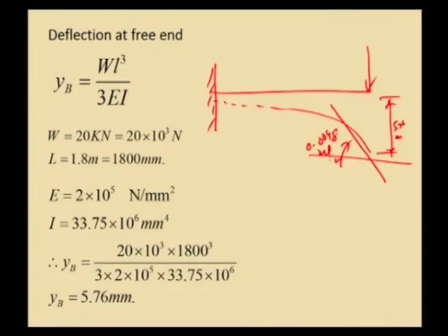So, to summarize, we have started with what is deflection, how do we calculate deflection and what are the equations involved. We have E I d squared y by dx squared equal to minus Mxx. Mxx is nothing but bending moment at any section xx. So, one should be able to find the bending moment in any section due to any applied loads. Once we are clear with finding bending moment and moment of inertia, then we can easily calculate the slope and deflection at any required point.